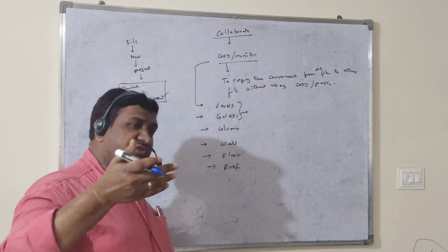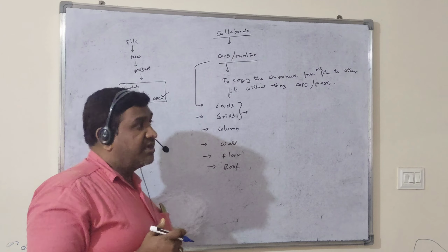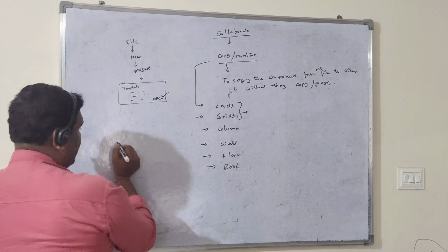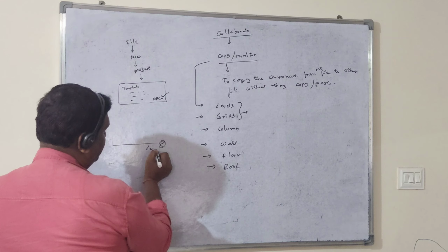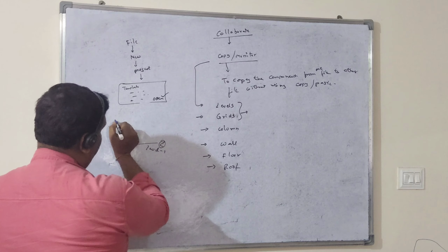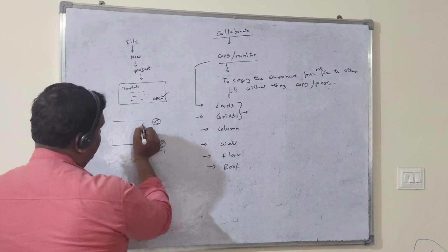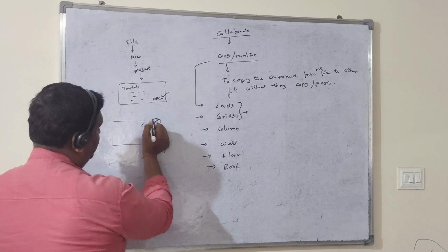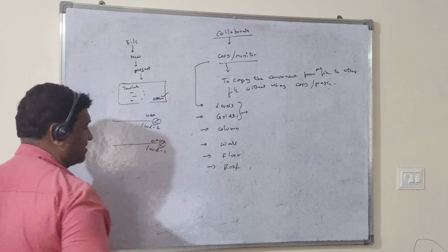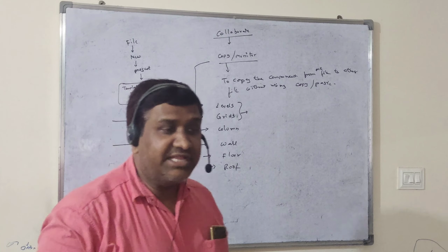So MEP people also, they will start the project this way. After opening, you have already seen here there are 2 levels coming by default. Am I right? Level 1 and one more level, that is level 2. Here the value is 0,0 and here the value is 4000. The 2 levels come by default.